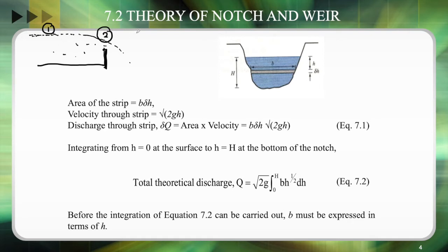So from here, we will apply Bernoulli's equation directly. P1 over rho g plus U1 squared over 2g plus Z1 equals P2 over rho g plus U2 squared over 2g plus Z2. From this, we know that the velocity at point 1 is 0 because it maintains at that level and does not reduce or increase. Therefore U1 is 0 meters per second.